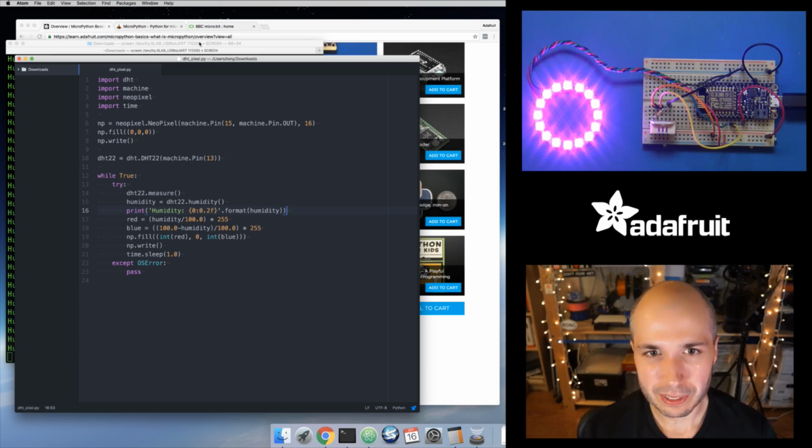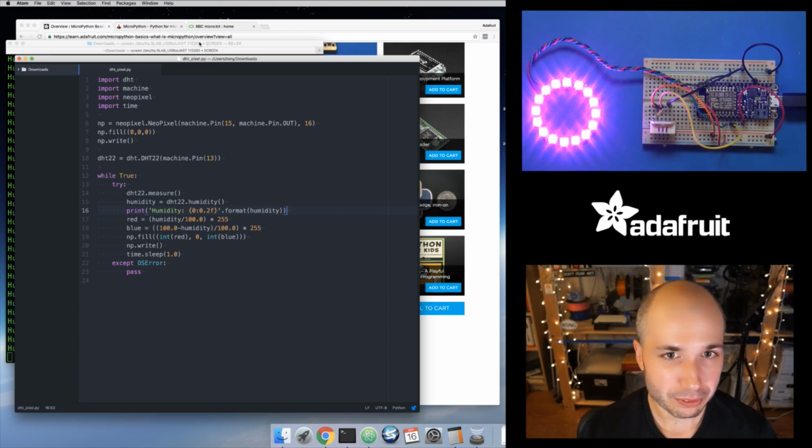And the cool thing, though, is that even though you can't have all of that functionality built in, if you need to add extra functionality, if you're interacting with hardware, if you are an embedded engineer and you like to get your hands dirty with C programming and assembly language and really talk to those peripherals at a low level, MicroPython can actually let you combine C code with Python code. So you can write C functions that your MicroPython code will call. And in fact, things like lighting these neopixels and reading this little DHT sensor, at a low level, there's a C function that someone implemented and is in the MicroPython firmware.